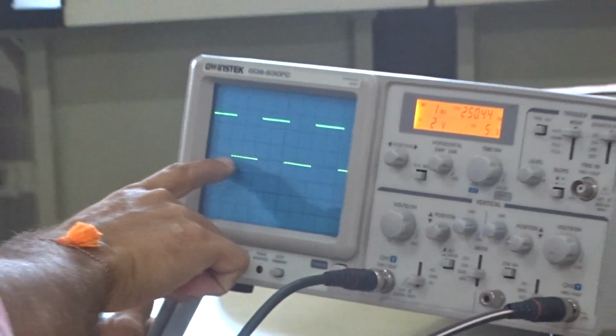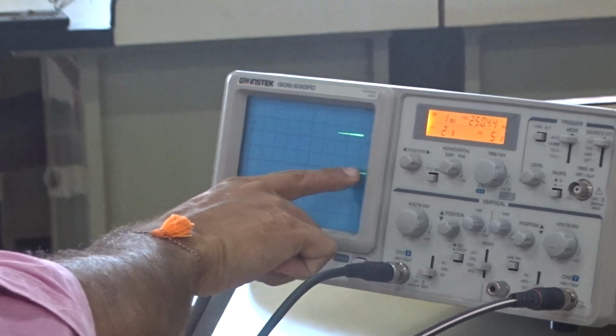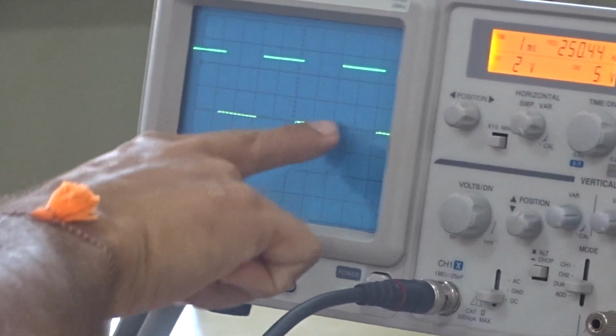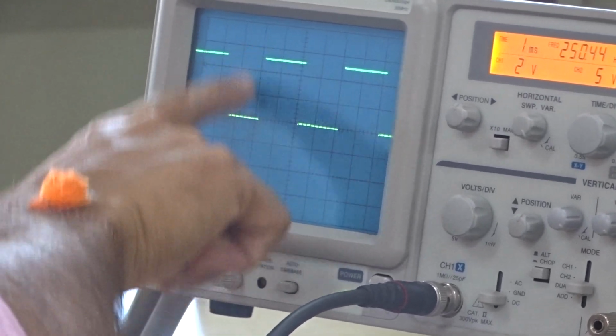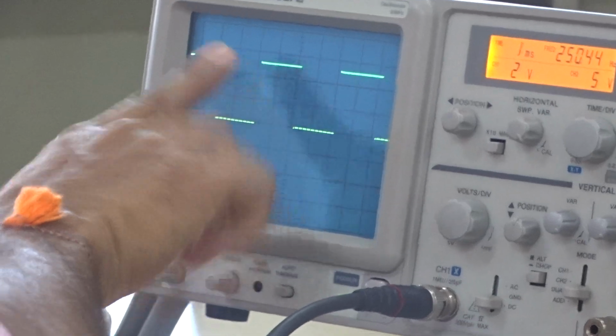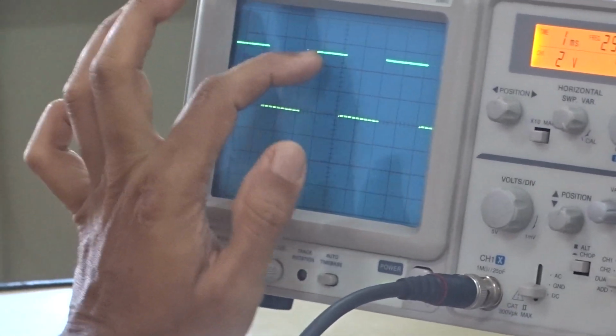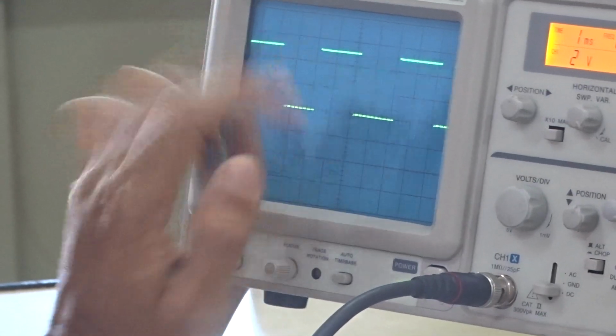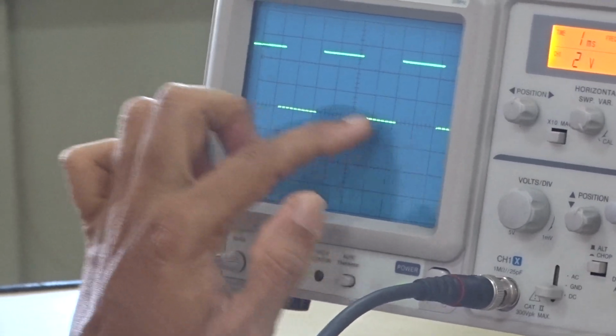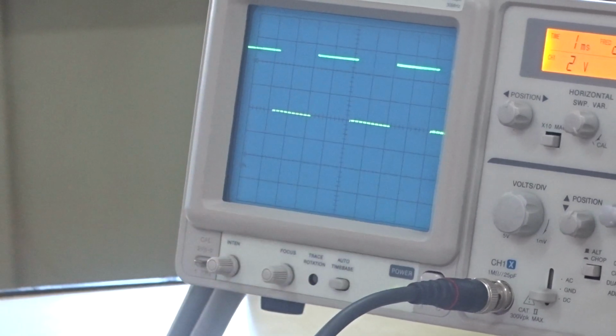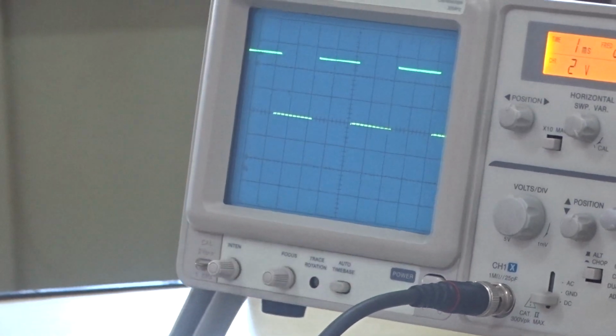Turn the knob and slowly increase the level. Now we can see that the negative peak of the square wave is on the time axis, our previous reference line. So the peak to peak amplitude is 5 volt now. So the square wave input, or message input, is set. Here bit 1 is represented by this 5 volt high level and bit 0 is represented by this 0 low level. Now our message is ready.